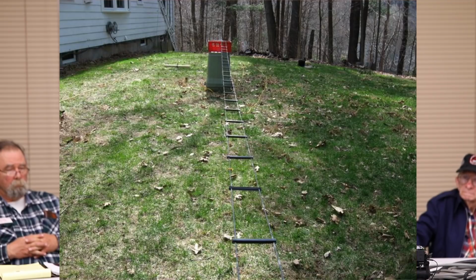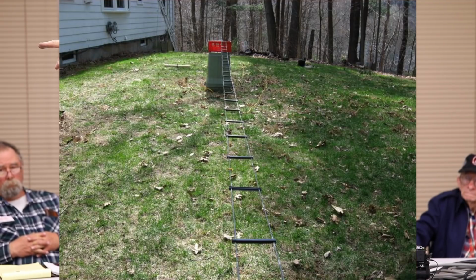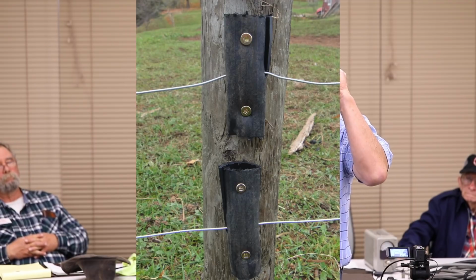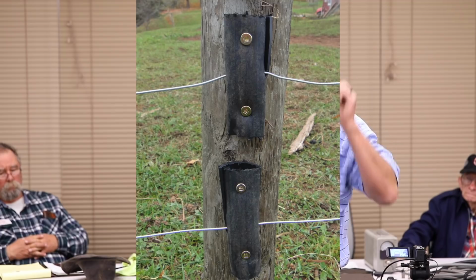And cheaper. You put the open feeder and you'd measure it and make it a 400 ohm or a 600 ohm, and you make your own little telephone poles and run that out there to your antenna, and it's very forgiving on the SWR. It's lower in loss, and it does a lot of cool things for you, but it's harder to work with. Oh, it's cheap too compared to that. If you're doing your UHF, VHF stuff, you can't do that. You got to buy something like this.